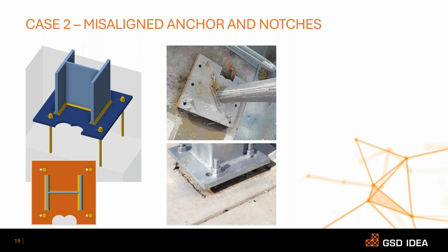So here, to resolve this issue, a straightforward and simple solution was to drill new holes and recheck the connection. And as the existing problems are not enough, we also have a bonus problem, which is a concrete obstacle here, as you can see, which will prevent the base plate from having a flat landing on the concrete. So we have to locally notch the base plate in order to have it properly installed at the site.